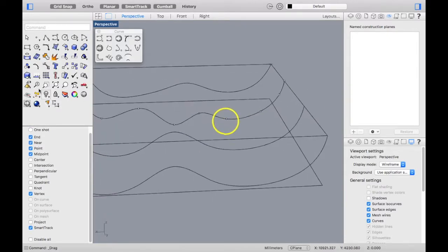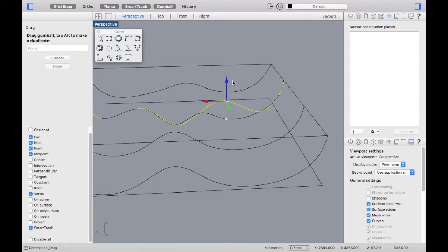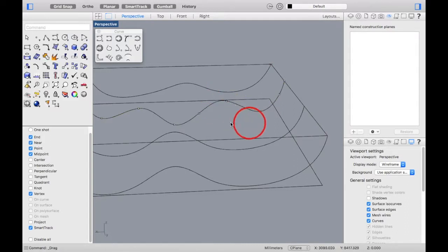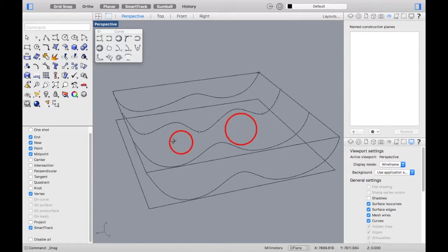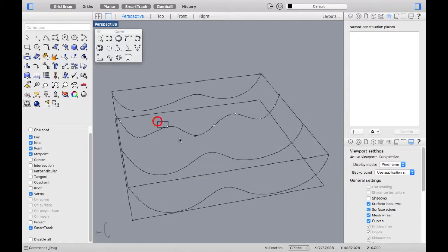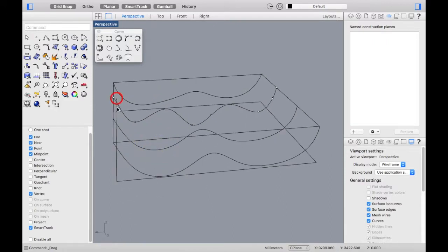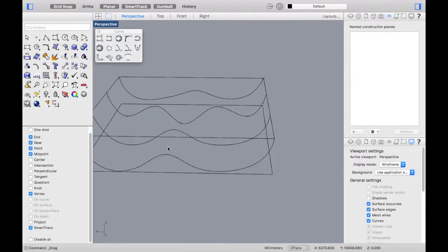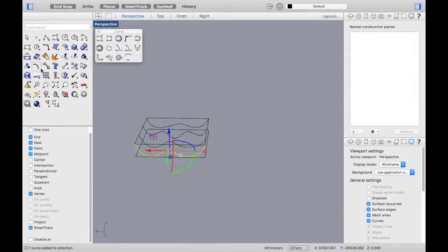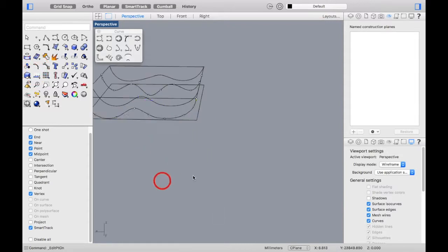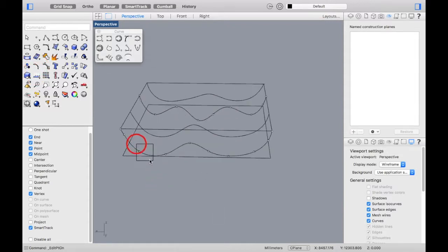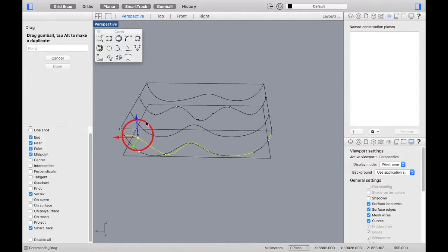Once we have our curves ready, which is we have our skeleton ready for the freeform structure, then we can give it a skin. For the skin, make sure your curves are not identical, so it gives out a more free looking form. So what you can see is all the curves that I have in my section are varying from each one.